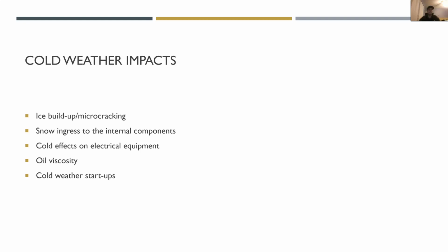As we just recently saw down in Texas, they opted not to have those extra backups installed, and they kind of suffered the consequences when they did have cold weather and they had no way to heat the turbines and they got iced up, and basically they had to shut them all down. So to avoid that in cold weather climates, it's a good idea to put some of those heaters in and make sure the turbines can operate year round without any major impacts.